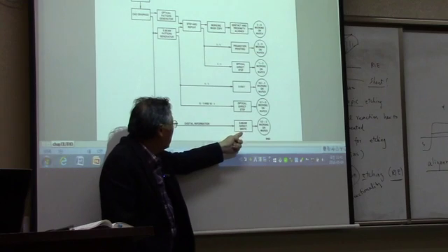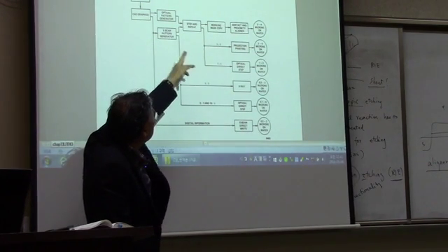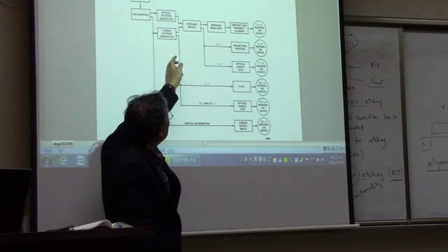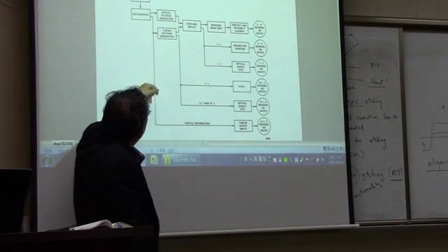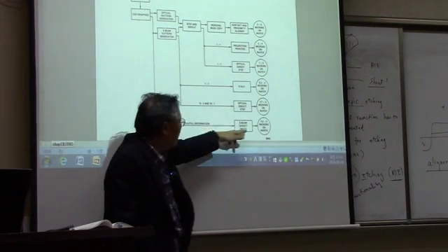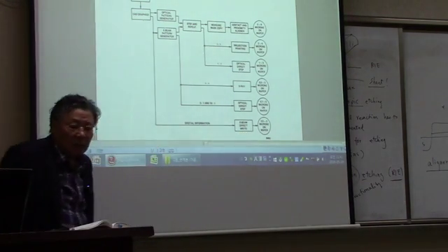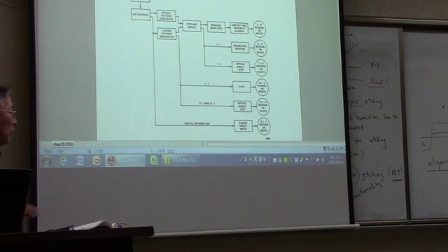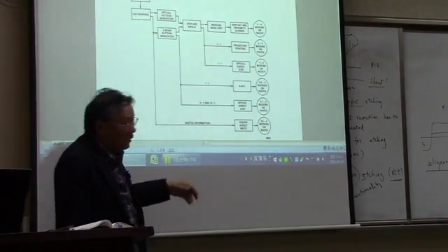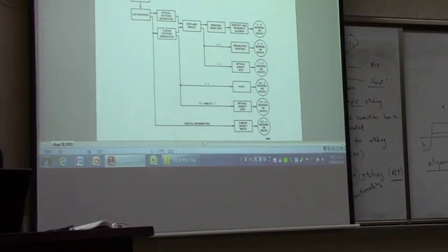E-beam direct writing does not need any masking steps, which consists of many steps here, okay? And it just comes from the CAD graphics, and that directly you use the E-beam to create the patterns. And we're going to discuss about this aligner systems in detail in a minute.